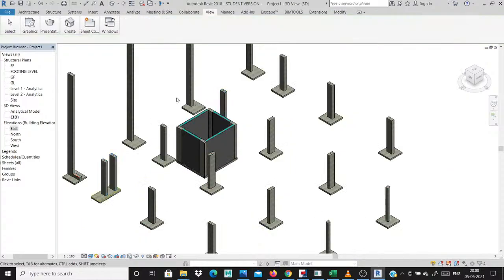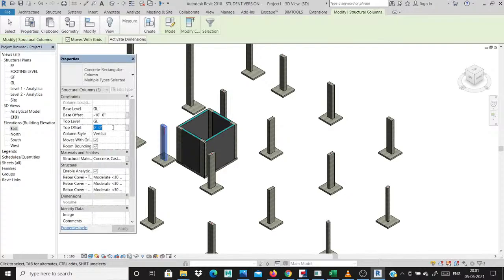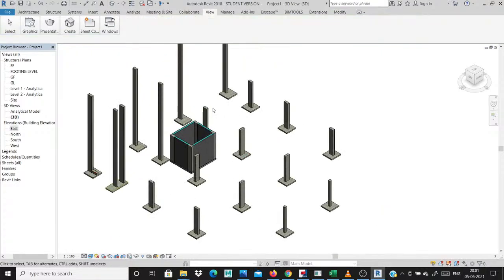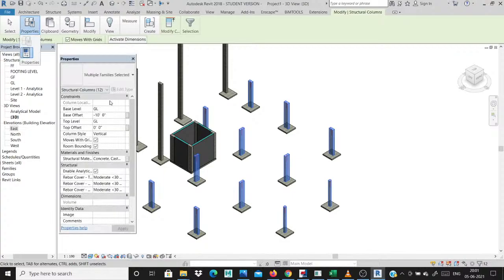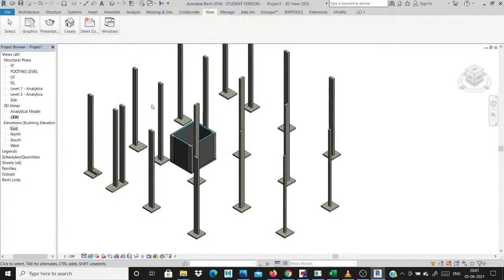Okay, this one I click this 3, then go to properties, then this is 30 feet, oh sorry, 20 feet. I simply click this 20 feet height. Then this also same, all the columns are increased to 20 feet height. Sometimes you will not be selected perfectly. I select all the columns, go to properties, then go to 20 feet, apply. Automatically our column will be created 20 feet.